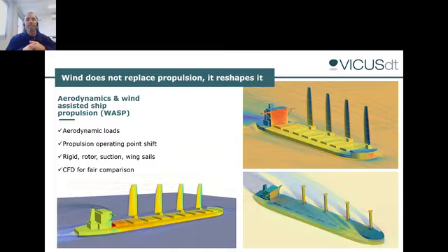So the CFD allows you to do a very fair comparison between technologies in your vessel, an independent assessment, and also to analyze at the same time what's going on and how it will impact my propulsion system, which is not a minor topic, because if you are obtaining a gain of 6%, but the propeller efficiency is going down together with the rudder by 3 or 4%, it is something to be accounted for very accurately.